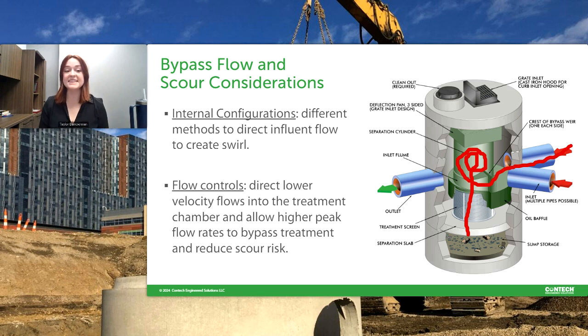So that means the sump is incredibly important. It minimizes scour potential as well as the resuspension of those pollutants. And the depth of our sumps was designed around testing for regular inspections throughout the year. However, just like not all HDS units are the same, not all sites are the same. You're going to have a job that has 3 different HDS units on it, and none of them are going to look the same. So when you're considering what your sump is going to look like and what your regular inspection times are going to be, you should be thinking about what site you're using.